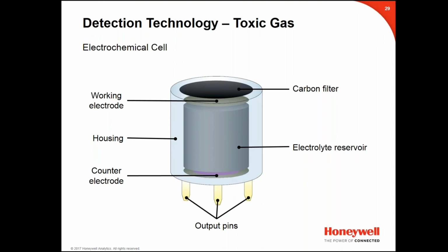This upper level, or this rising alarm level, is associated with 23% by volume because that level of oxygen and higher makes typical materials more flammable, easier to combust. At 25% by volume, it doesn't take much energy for your clothing to catch fire. And so that's a real concern.